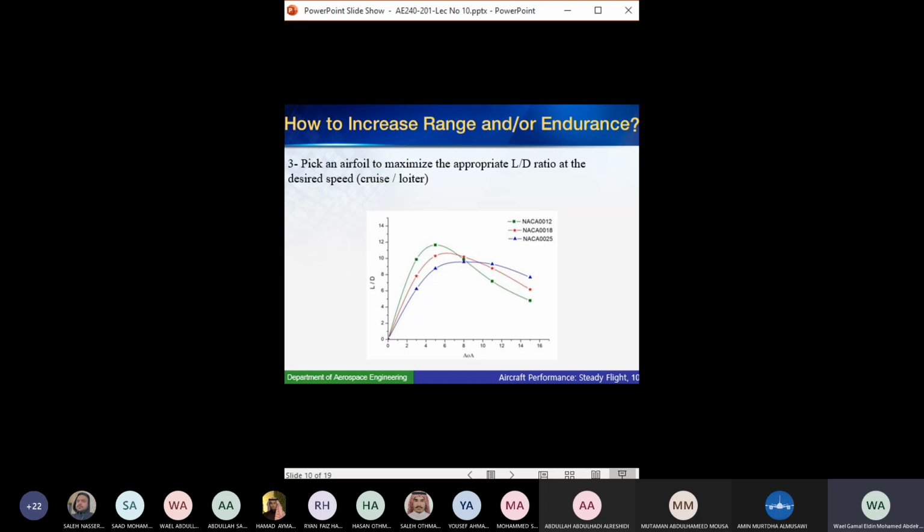Okay, let's divide them into steps, just like we do in quizzes online, where we have to divide it into steps. From the speed, can you get the CL? Yes, the CL is equal to the lift or the weight, because they are the same, divided by 1/2 rho V square S. So that will give me the CL.